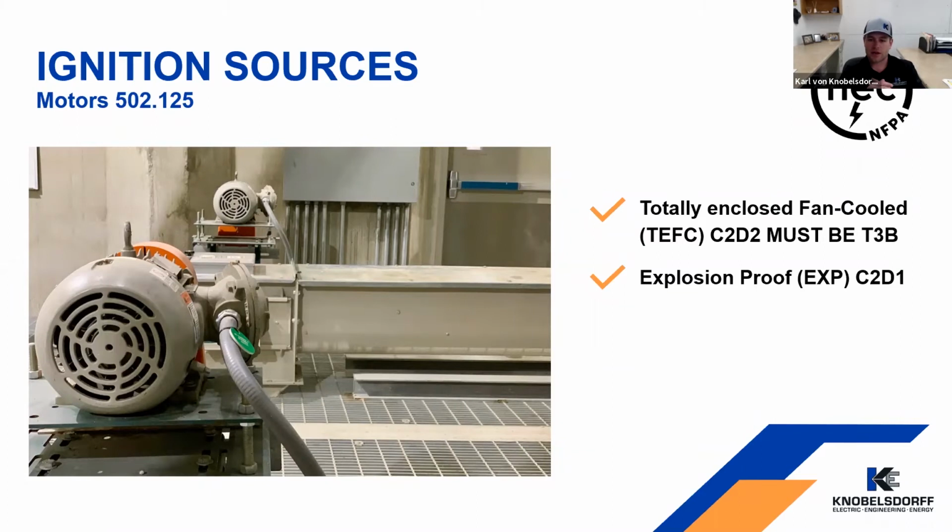And if we're in a class 2 div 2 location, a motor has to be totally enclosed, fan cooled. But there's also another caveat to that: they have a temperature code rating that you have to look at on the motor. So you can't just take any TEFC motor and use it in a class 2 div 2 location. You have to look at the temp code rating, and that temperature code rating has to stay under a certain class, which means that the surface temperature of that motor can't get over a certain temperature depending on the group of dust that you have in your facility.